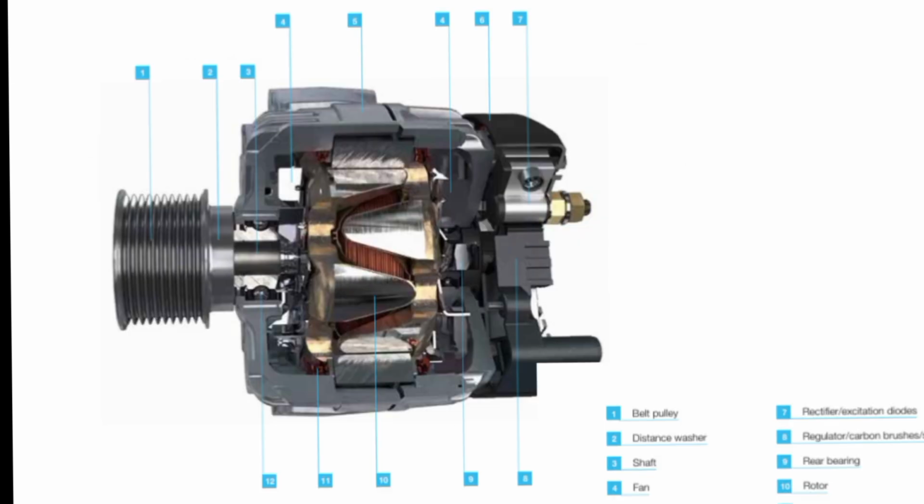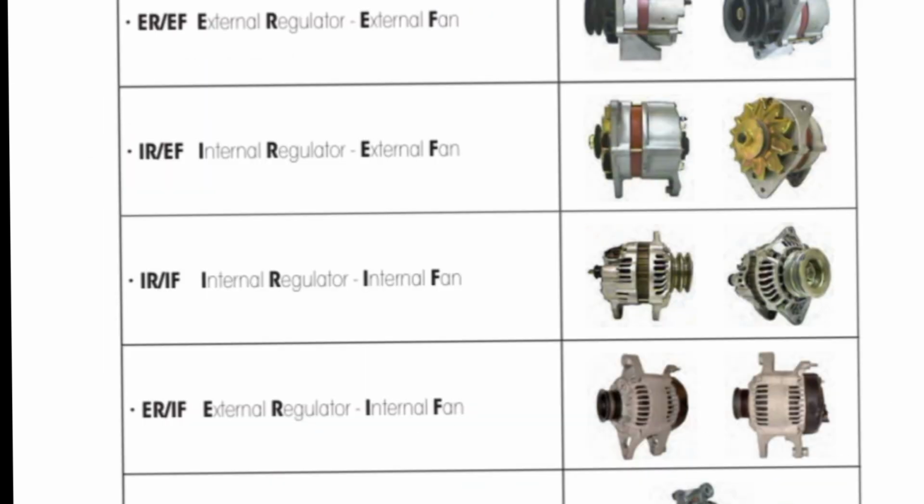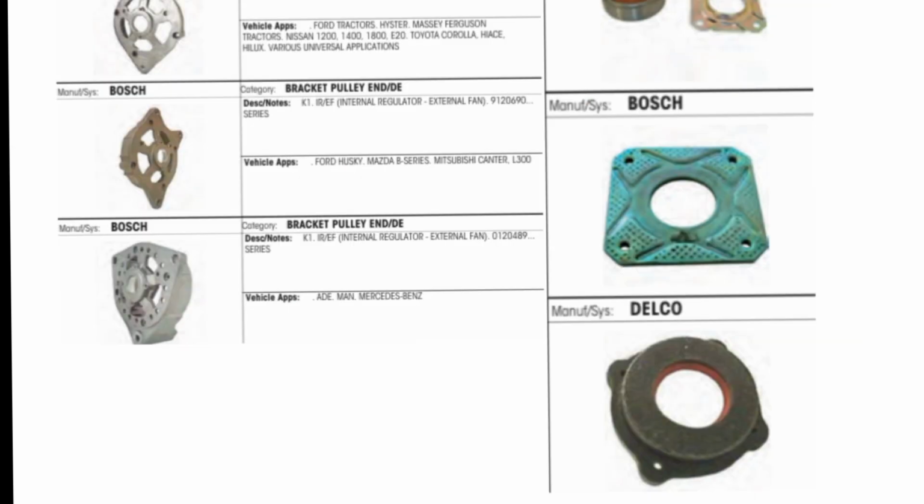Normally charging voltage will be around 13.5 volts to 14.5 volts in 12V systems, and 27 volts to 28 volts in 24V systems.